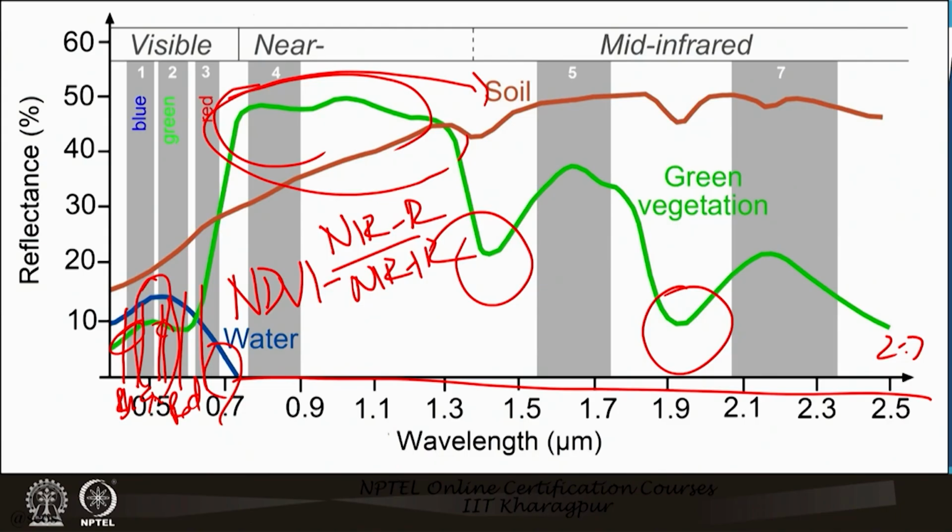near infrared band, and wherever it is 0 or a certain value. It may not be exactly 0, because there may be certain characteristics of that particular water body which may be emitting a certain amount of energy. There may be plants, etc. So you look at that range of digital numbers, and it can be easily separated as water and non-water. That is called thresholding.